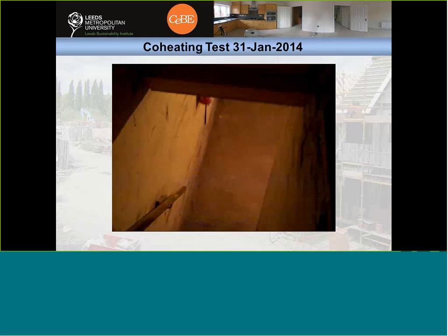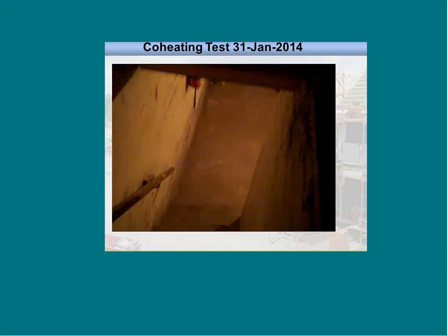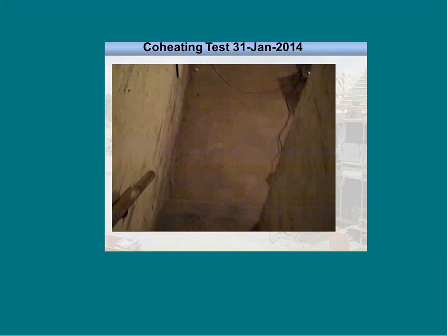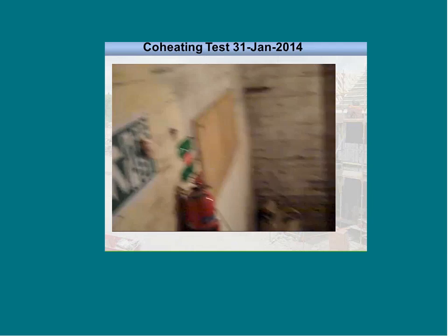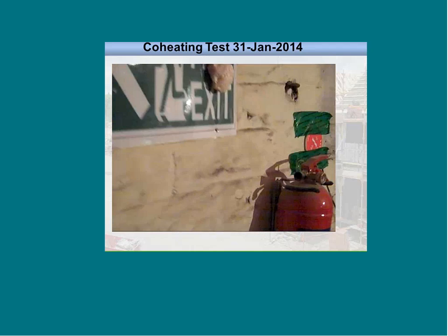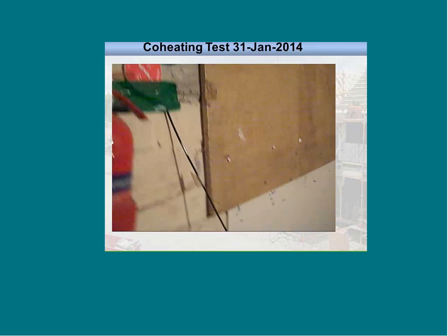To estimate, for example, the heat loss coefficient, which is the most important parameter, and the solar aperture coefficient, we need to apply linear regression, assuming this equation and assuming the collected measurement data. Three options present themselves here. First, we have the simple linear regression on the basis of the equation on the right, on top of the graph. How do we get to this equation? We make an assumption on the solar aperture coefficient, and we take the solar gain term to the left-hand side of the equation. This way we can relate a kind of solar corrected heating power to the temperature difference between inside and outside during the test. The sole result of this simple linear regression is then the heat loss coefficient.